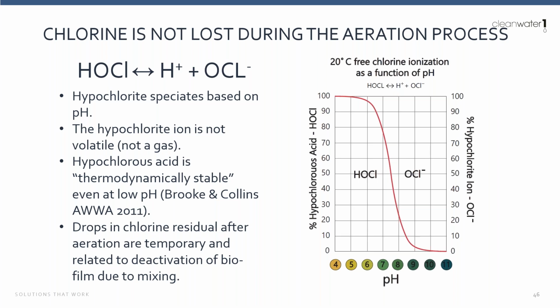After we did that, my professor, Robin Collins, a master water chemist with much stronger water chemistry than I have, I'm more of a physics guy, came up with some good theory as to why that is the case, and that's in the peer-reviewed paper that I published. In the intervening years, that was back in 2011, there's been other publication on this, and I can think of a couple of papers that have looked at this, and they found no effect. AWWA weighed in on this in their distribution system manual of practice, I think that's M63, 62. And they said, yep, we really have seen no signs of chlorine coming out during aeration.